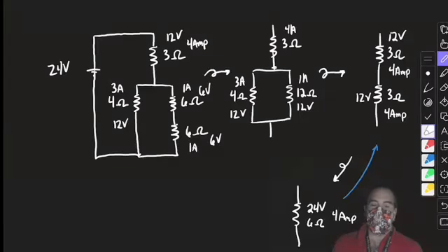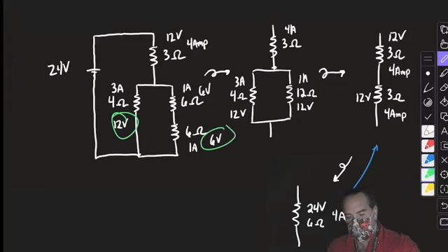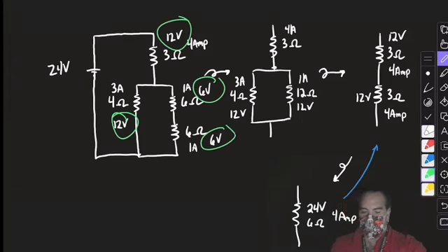All right. There are 2 super common misconceptions. And if you make these mistakes after I tell you about them, I'm going to laugh at you. There's bound to be somebody in the room who wants to go through and add up all the voltage and tell me that if I add up all the voltage, it's more than 24. Sure is. It's 36. You can't add up all the voltage and see if it equals the voltage that was there before. That's not a rule. That was never a rule.